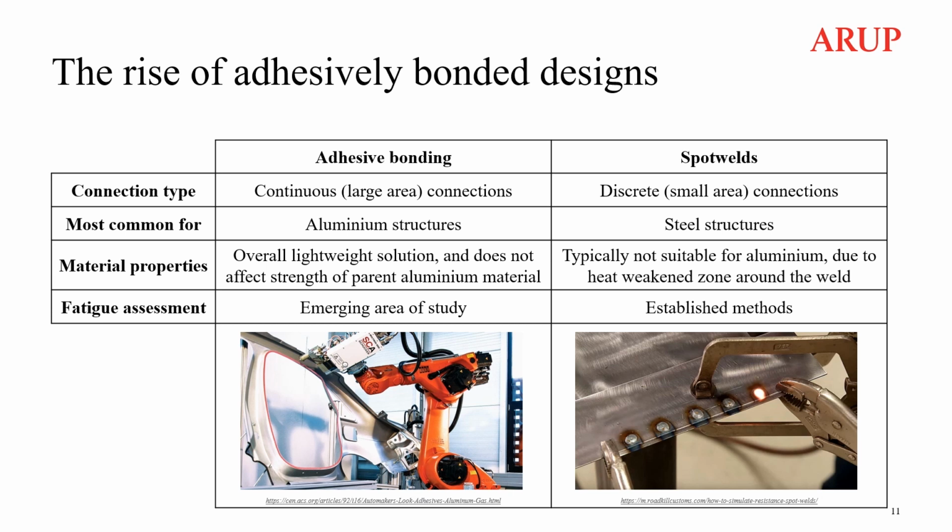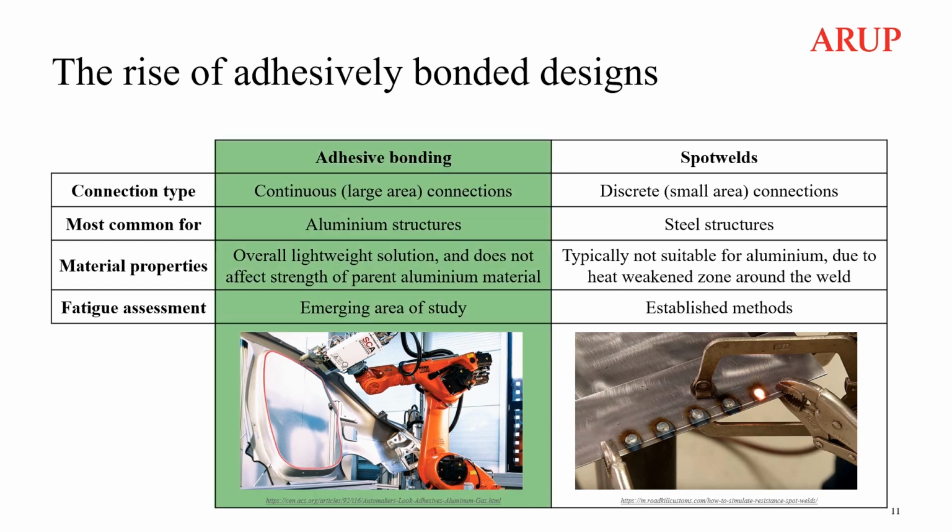Stress concentrations occurring around lots of small spot welds would be expected to be more severe than those occurring around large, smeared areas of adhesive bond. Adhesive bonding of aluminium battery enclosures is the focus for the rest of this presentation.